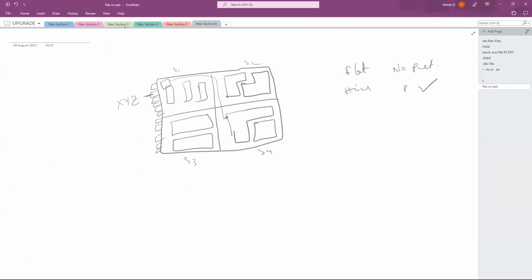Creating a particular clock does not mean you are creating the clock through the SDC. Your clock is already created. You are telling the tool, I'm creating the clock from this particular clock source, and it is going through this particular port and so on. You're just telling the tool how the clock is going, then the tool will calculate in the respective manner. So create clock, create generated clock.